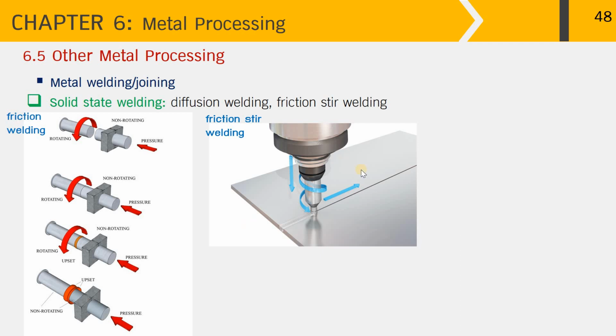For example, if you want to weld two metal plates together, in the process of friction stir welding, while putting on the pressure or the load through the pin onto the metal sheet in the butt joint configuration, the pin is rotated at high speed and moves in the forward direction. By this means, we can produce the weld line that can give high mechanical strength.